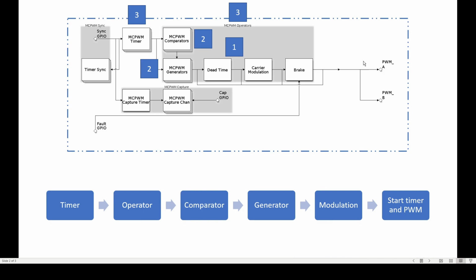In this example, if you apply both of them to PWMA, you cannot apply any to PWMB. Another case is you can apply the rising edge delay, or positive delay, to PWMA, and for PWMB you can only add the negative delay, or falling edge delay. So like that.